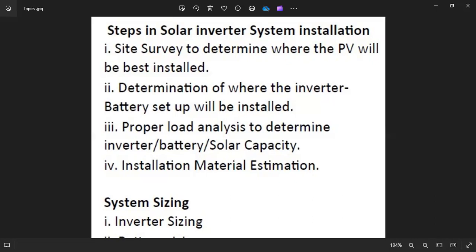If you're installing in Yola and it's within your capacity, you are designing a solar stand or a solar rail that will enable you to harness the best possible power from the sun. You have to make it at an inclination angle of 12.49 something. Around 12 degrees should be the inclination facing south. You understand? That is the best position.